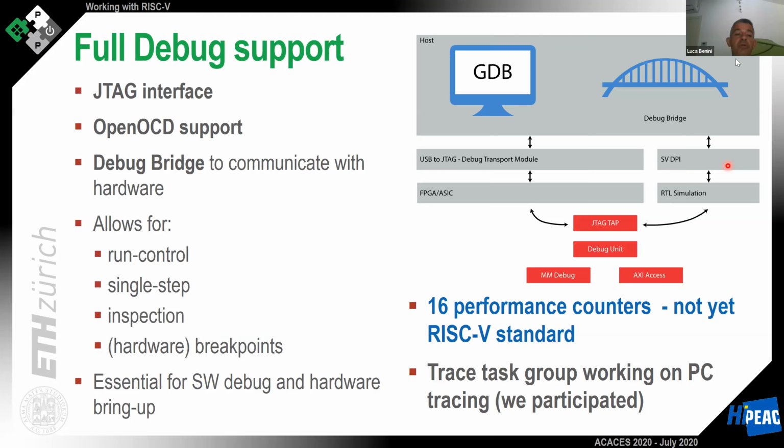So one very important point that comes with designing an application level processor is to be able to provide programmers, both in the debug phase, but also most importantly in the application level development and optimization phase, standard interfaces to debug and trace. So the standard debug bridge is supported for Ariane, as well as a number of performance counters that are useful in optimizing applications, such as tracking the number of cache misses, issue rates and things like that.